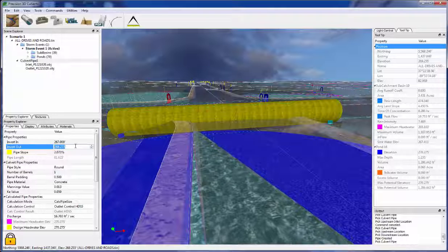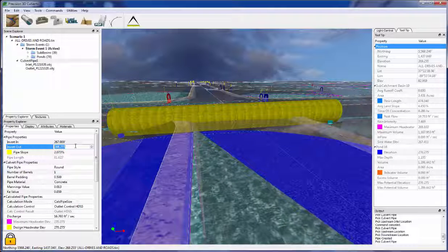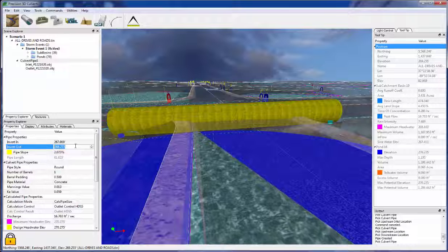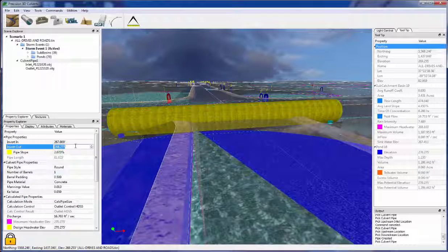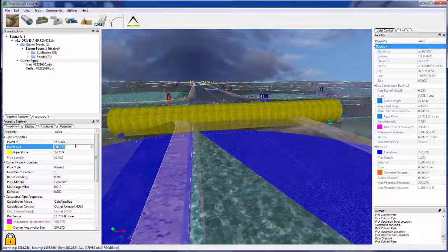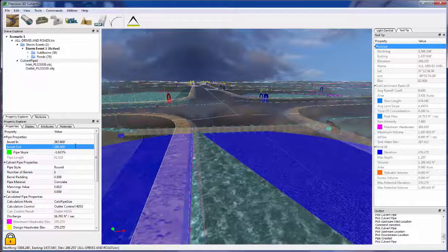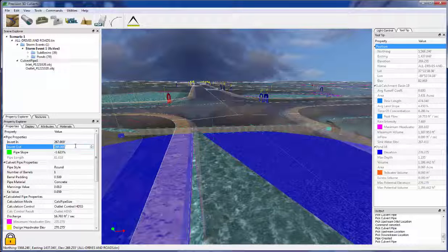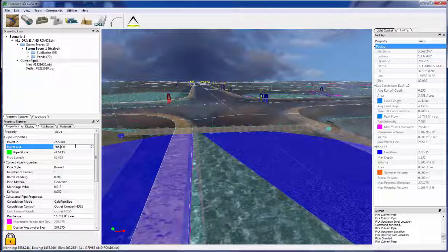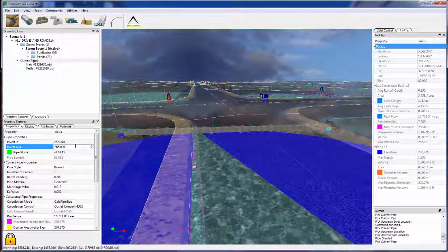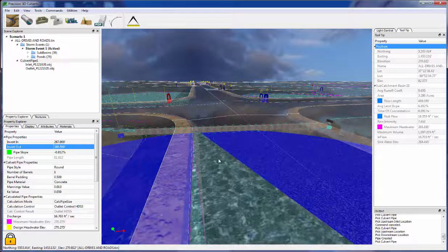And you notice that we're getting a different pipe calculation. And again, that's because we're a dynamic, interactive environment. All the changes that you make are instantly visible, but we'll fix that up here pretty quick. We'll make sure that the thing's going to drain going down to a 266. We could even bump that up just a little bit to have the slightest of slopes.